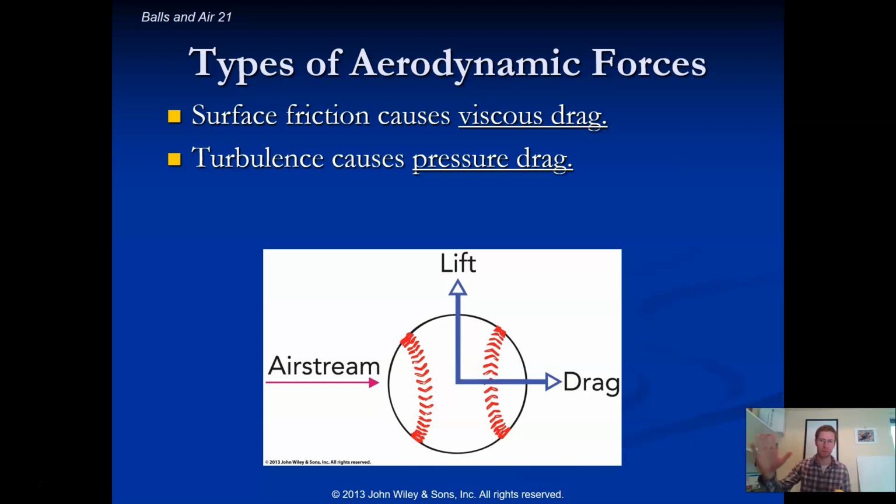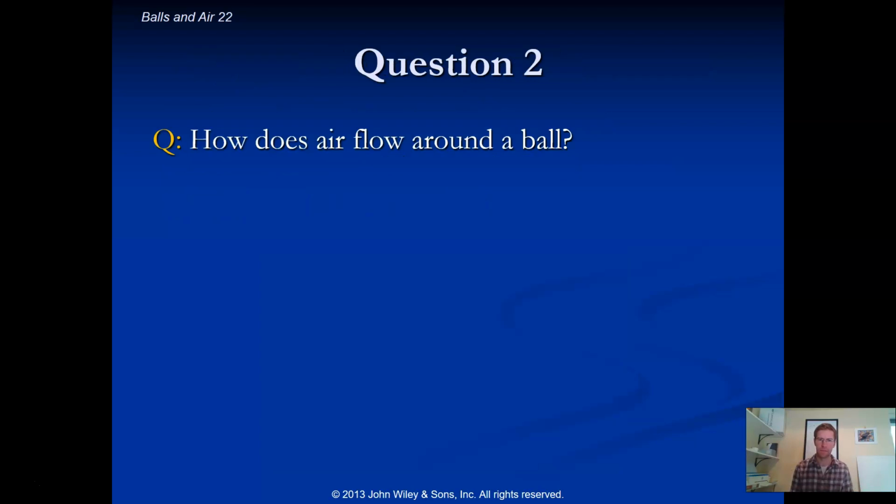There's another name for drag forces, and drag forces can be broken up into two types: viscous drag, which is friction with the air, and pressure drag, which is generated by a pressure difference on either side of your ball. Okay, and then when you're deflecting or pushing air up, down, left, or right, as you deflect the air, it will also deflect the ball in the opposite direction, again, conservation of momentum. And so these forces that are perpendicular to your direction of motion, we call lift forces.